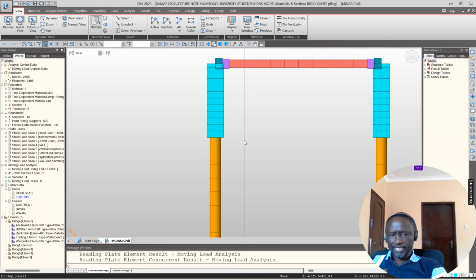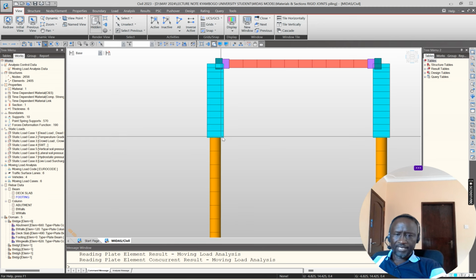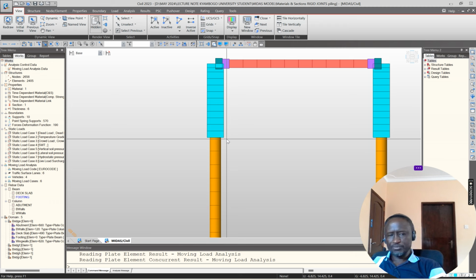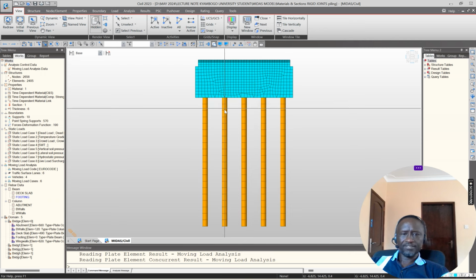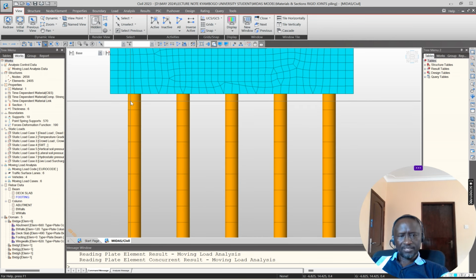you know the edge distance, you know the center distance, spacing. So from the center line of this pile to the end should be about maybe 1.25 or 1.22 depending on which code you're using. And then if you have like this, the center line could be between here and the edge about 1.25 or 1.22 or 1 normally as minimum. Then the spacing between these piles should be at least 2.5 or 2.2.